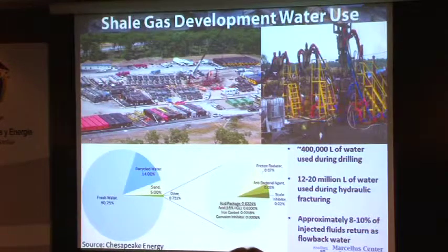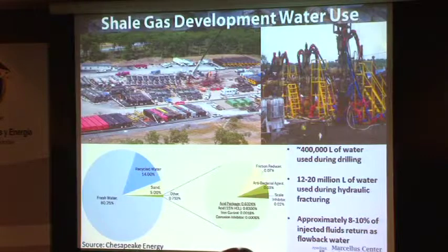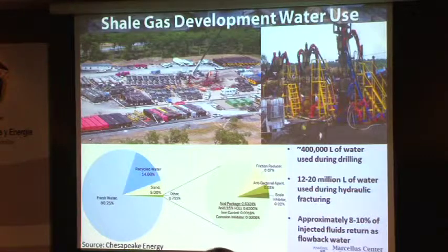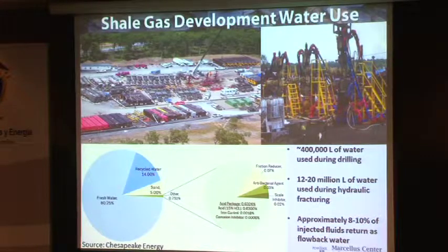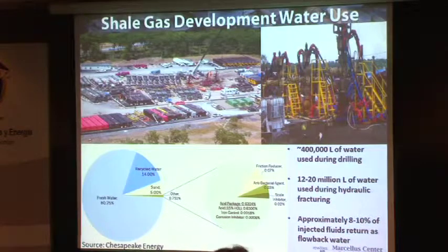Very importantly, there's a control van where they're monitoring the fluid injection rates and the pressures to make sure everything's going according to plan. And so that's really a critical part of this, because if something were to deviate, say the pressure were to drop suddenly, the engineers on site would want to make sure that they understand what's going on in case they need to shut down the operation for some unforeseen reason.